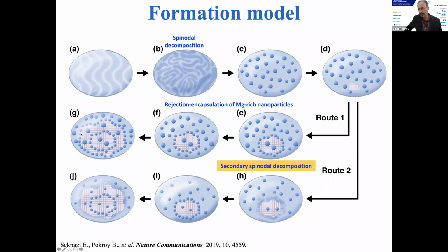And there are two possible mechanisms which might be working in parallel. One, you have these nanoparticles now, these nanoprecipitates, which are amorphous. Some of them get attracted to the crystal, which propagates. Some of them get pushed out. As you are pushing them out, of course, locally, you are changing the concentration of them in the solution. And then again, you have them being attracted and pushed out. And that's how you get these alternating layers of different concentration of these nanoprecipitates. And as the crystallization front goes through, it actually just goes through the matrix as well as these trapped nanoprecipitates.